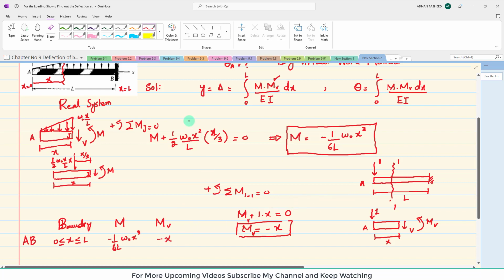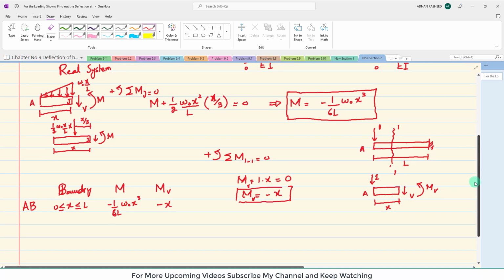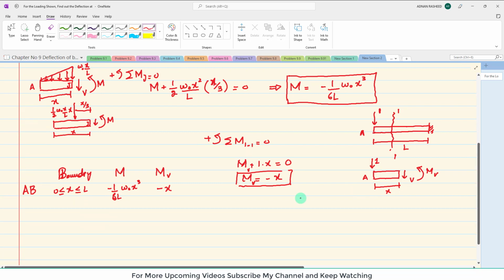Again, here we are first finding deflection, so it's only for deflection. For slope you have to apply a unit moment at this point. When we move further, you will clearly understand it.